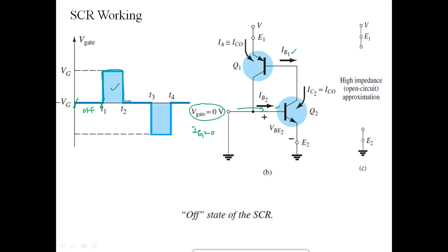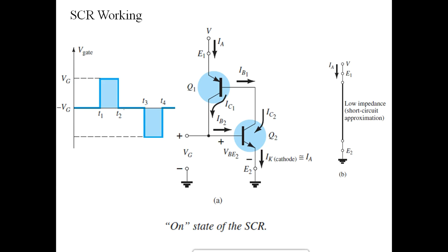Then what happens during this particular pulse? During this particular pulse, the SCR will be on. Just observe, from T1 to T2, when Vg is being applied, Ig flows, and when Ig flows, the transistor will be on. Since NPN is on, simultaneously PNP will also be on. The previous explanation that I did was with respect to the device physics, what is actually happening inside the device. This explanation is circuit wise. Now both the transistors are on, so a continuous current keeps on flowing.